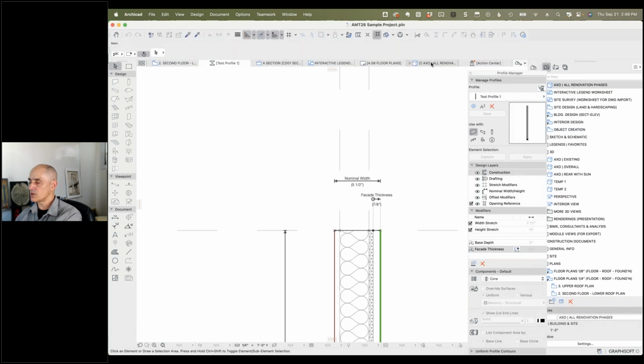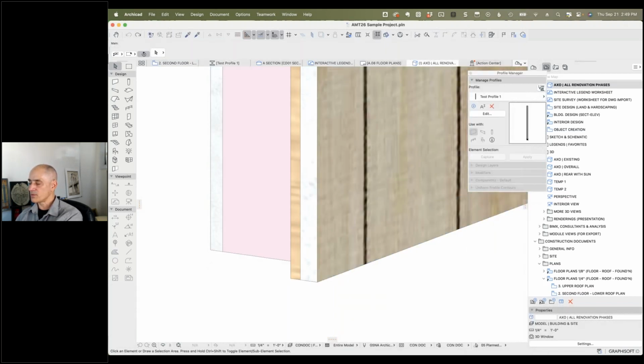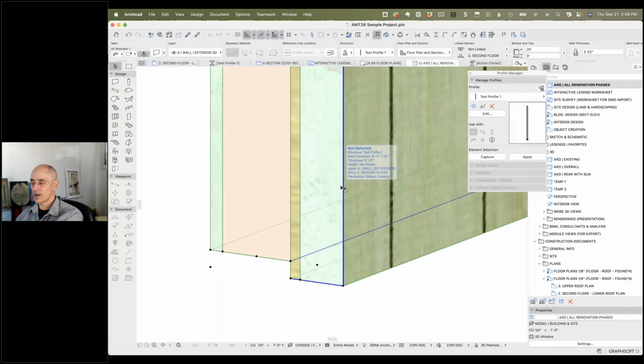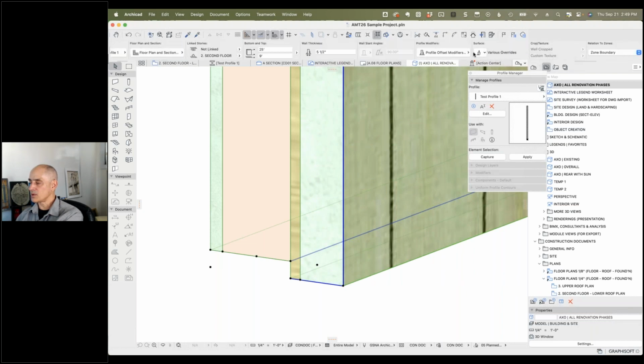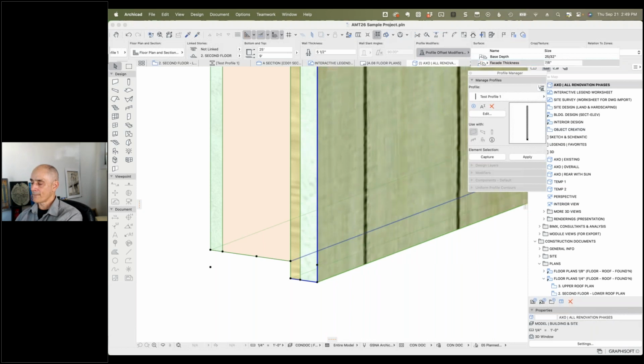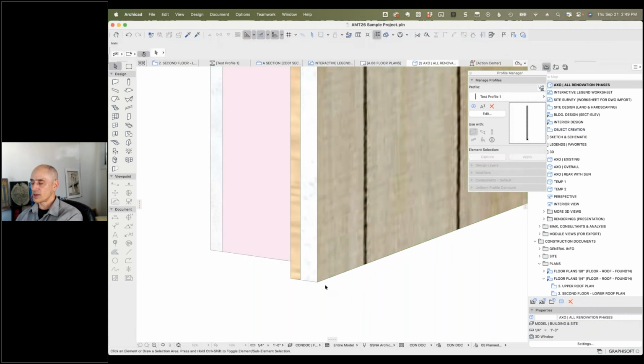And now if we go to the 3D, we're going to see that this now has a blue line here. I can literally just thicken that, and I can type in a value in terms of the offset modifiers. The facade thickness, I can say it's going to be 1 1/2 inch or something like that, and that controls it. The original one was 7/8 there. Okay, so you can do that, but obviously you wouldn't want to match one side and the other. That was just a demonstration. So is that relatively clear? Yep. Yeah. All right. Okay.